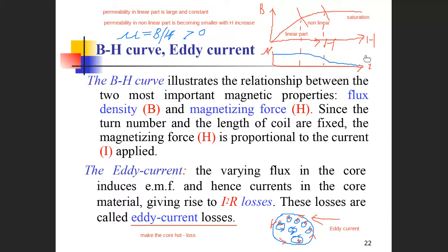In practice, we use the current and induced voltage to get the BH curves. From the BH curves, we experimentally find out the permeability of a given material as a function of the current I, which is used to estimate the inductance of a given coil in practice, because it is changing with current.